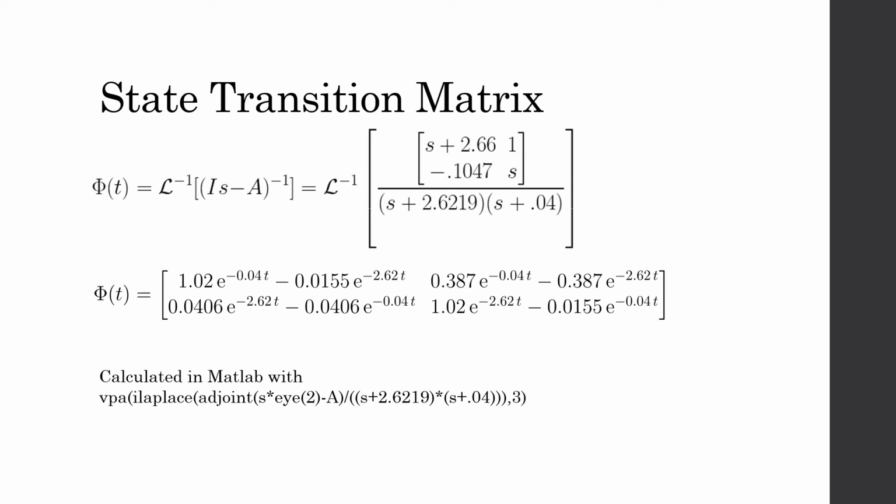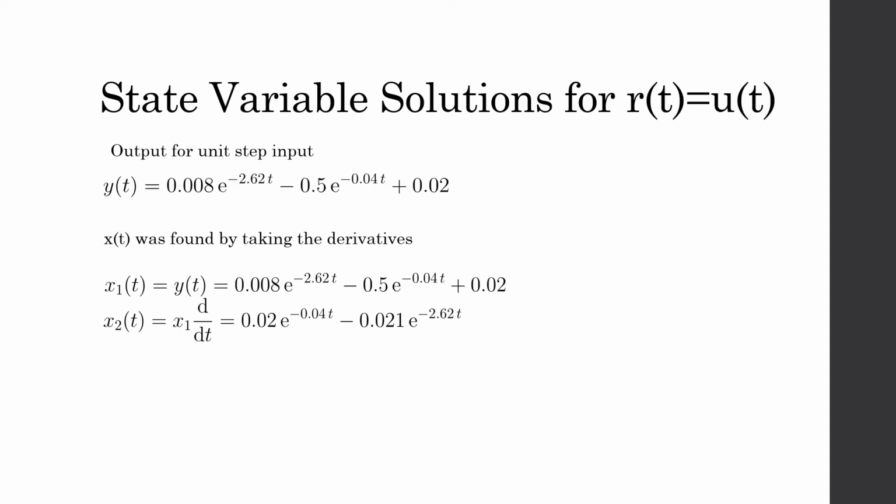The state transition matrix can be calculated in a variety of ways. Here it was calculated by taking the inverse Laplace transform of the inverse of sI minus A. This results in the following state transition matrix, and it was calculated using the following commands in MATLAB.